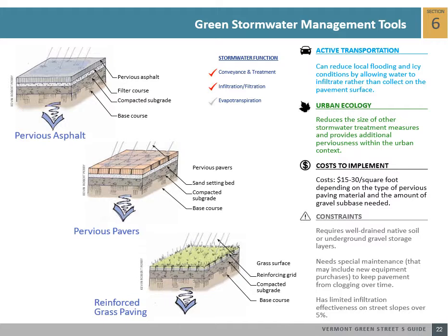Planters can be used in both relatively flat conditions and in steep conditions if they are appropriately terraced. Because they tend to have small footprints, they are best used to control small volumes of water and should not be installed where heavy runoff flows are likely.